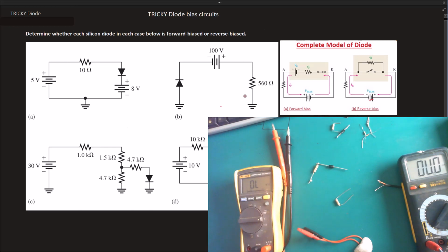Now I'm going to do a small trick here, which I do not recommend for anyone to do at home. I'm going to use a variable transformer that I have here, connect a full wave bridge rectifier, and tune the RMS voltage up until I get about 100 volt DC on the output, and use that to test this particular diode, which is going to make this next experiment a little bit dangerous. So not recommended if you do not know what you are doing.